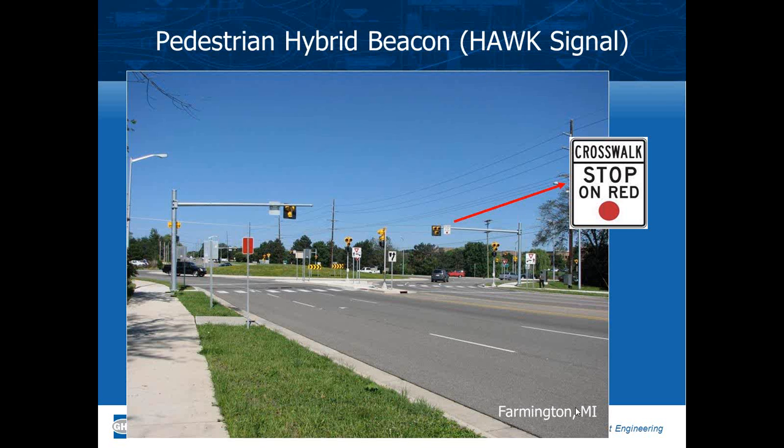This was the one that was retrofitted in Farmington, Michigan. Oakland County was the county that had the lawsuit. In the courts, they decided that they should install these as a pilot installation and study them, and then report back to the courts on their use and success or lack of. What they found in the before and after study is that there were too few pedestrians to really form any statistics or any conclusions of their benefit. So even though this represents an accessible crossing for a 2-lane roundabout, there was really no evidence that it either improved safety or was desirable.